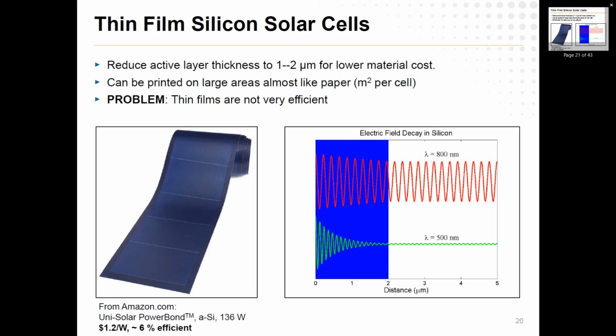So that's pretty cool. What would you rather have? A perfectly 100% efficient solar cell that costs $1 million for every square foot, or this 6% efficiency that costs maybe $2 or $3 per square foot? We'll just make more of it, and land is cheap, so make a really big solar farm for cheap rather than a small one that's expensive. But the big problem is that thin film is great and cheap, yet there's so much headroom on my efficiency. I could, in principle, triple or quadruple it and still not quite reach that Shockley-Queisser limit.